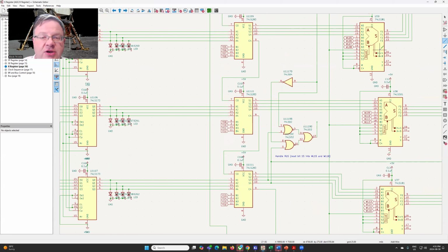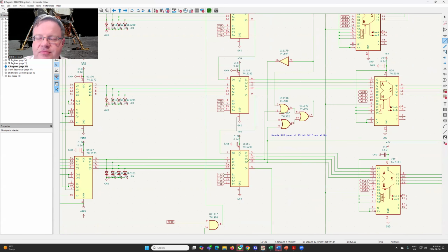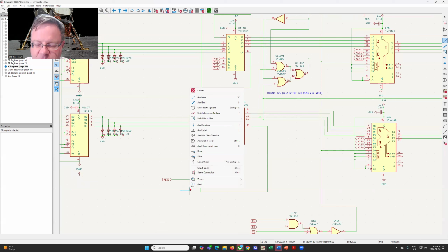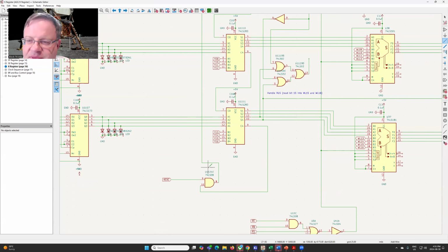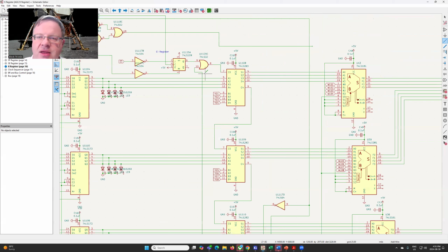So that's very similar to what we had to do on our A register. So we'll cover that in the next video. But what we do here, like I said, we've got our cascading carry all the way down to the end where we have our NIAC signal, which is where we basically determine whether we need to do the end around carry, which is all the way from the high bit 16 all the way back to bit 1. Now, in addition, we also have our CI register, where we can store that carry based on the CI control pulse.